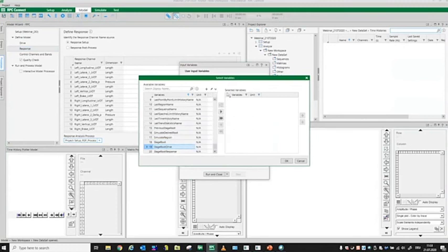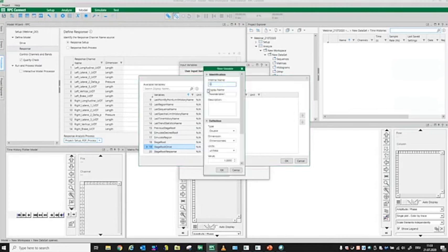And if you want to have your wildcard as you had in RPC Pro, like user 1 or whatever you used, you have not only user 1 till user 8 or user 6, what we have. You can just say, okay, create a variable and call it user 1, and say my display name is user 1. You give it whatever reason or way you want to use it, depending on you. You can call it just a string to have it as a placeholder, like a time history file name, for example, and you type in something you're interested in, or you can say it's a double or a Boolean value, and then you hit OK.